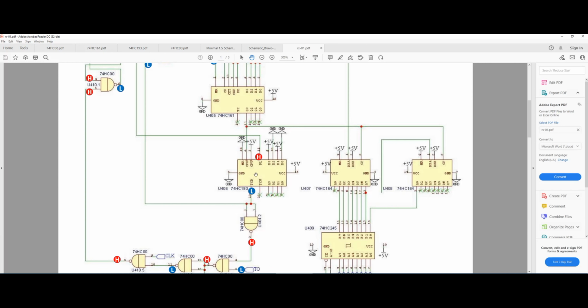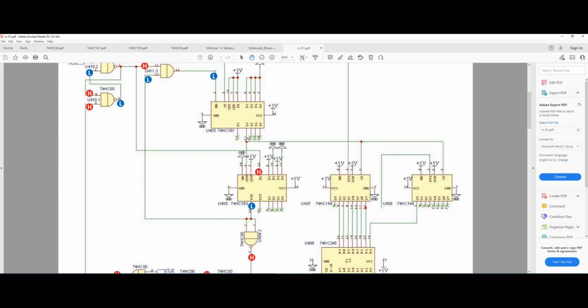All right? So now let's have a quick look at the other pins. We have a master reset pin, which is tied to ground, and this actually requires an active high to be reset. Therefore, this chip is not reset. However, it requires a clock pulse to come into the chip, which currently is not counting. It comes from the clock divider, as you can see.